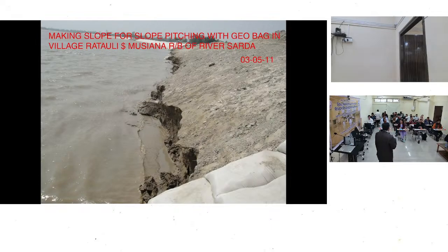Again, because of the flood conditions and the silty type of material. See, most erodible is the silty sand, the SM type of material. Silty sands are most erodible. And finally, the river banks of the Sarda river had a lot of erosion problems.